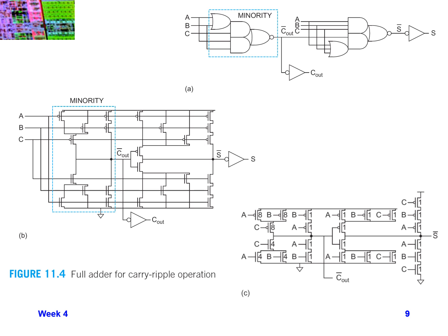The logical function that we had on the previous page, you can see you're doing an OR of A and B, and then along with A, B, and C, that AND OR function is what gives us the C out bar, and then that leads into the second stage where we're calculating the sum. And again, you can see C out bar comes out in a single stage.